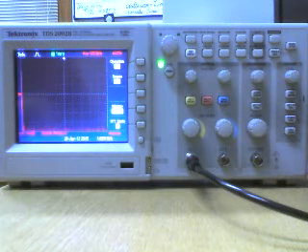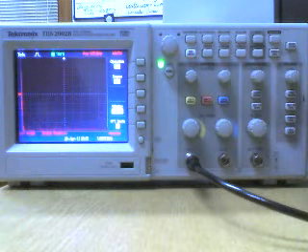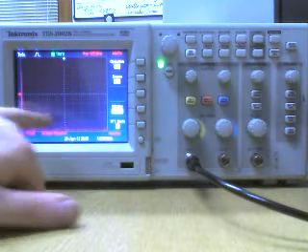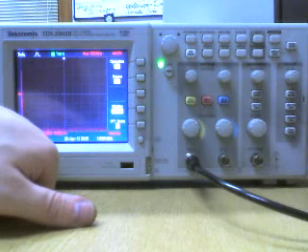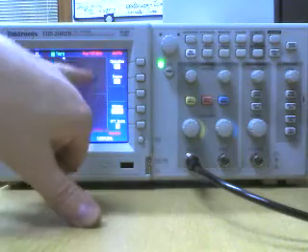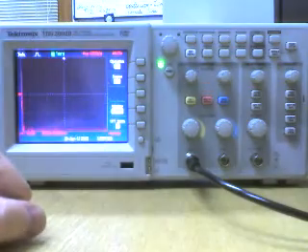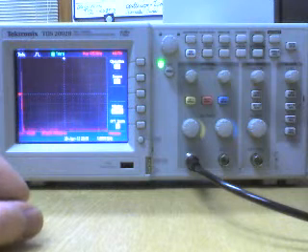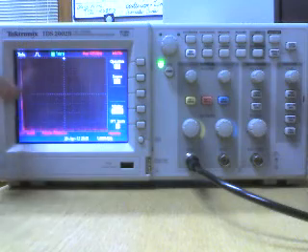At the moment I'm feeding in a signal of 2 volts peak to peak at 1 kilohertz. This is set to 25 kilohertz per division, and the centre of the screen is at 125 kilohertz. Well, that's miles above 1 kilohertz, but just down the side of the screen you can see a spike. This is where the 1 kilohertz signal is.